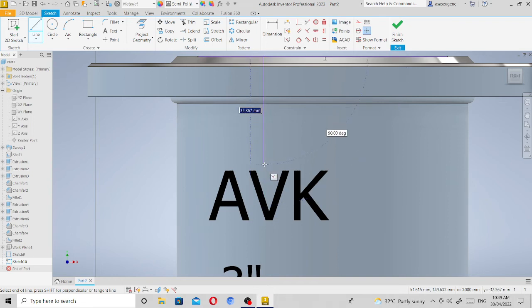It's indicated in the activity that the distance of the tip on the top of the text from the topmost part of the geometry is to be 40 mm. Let's make sure that it's 90 degrees. 40, enter.